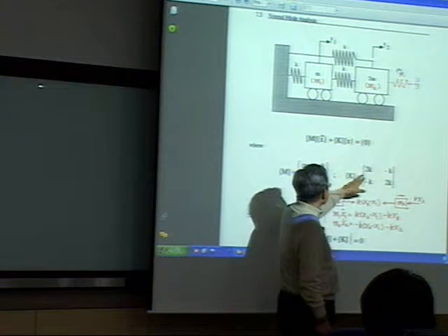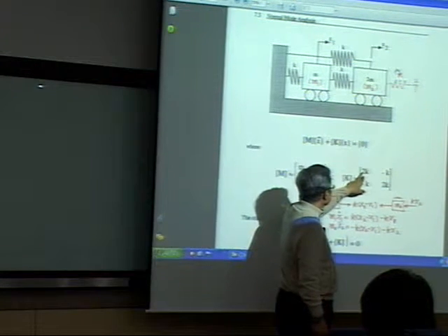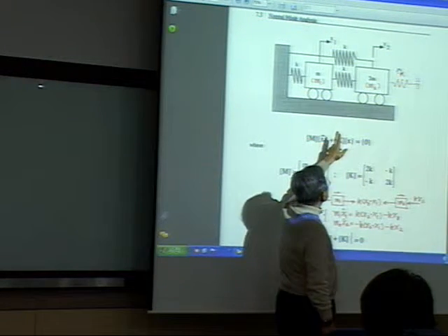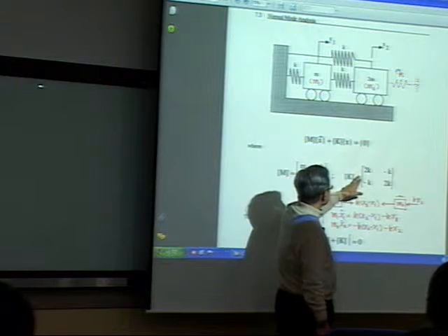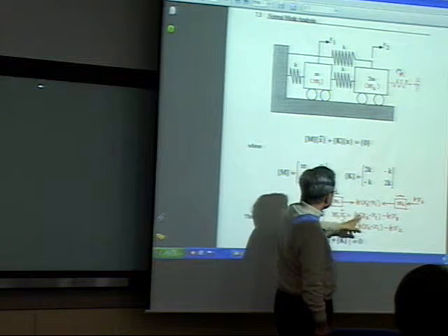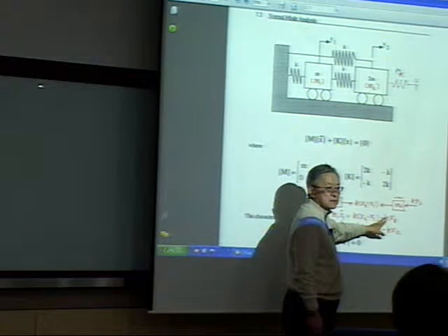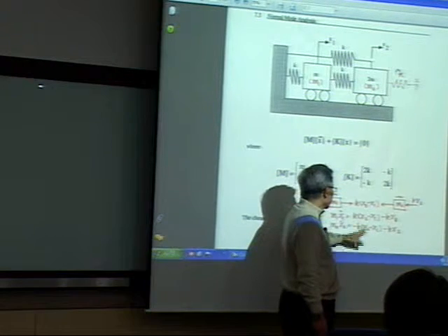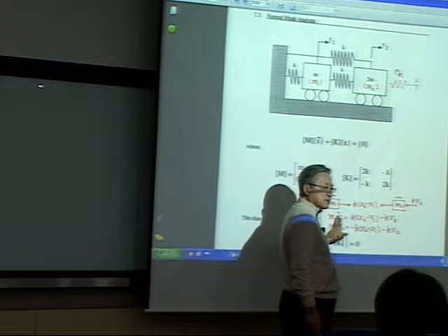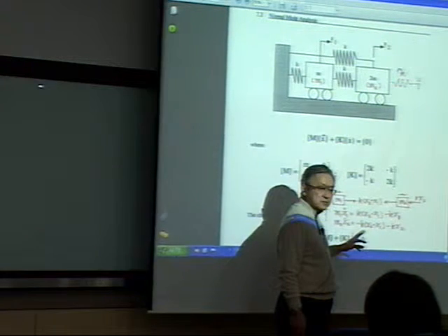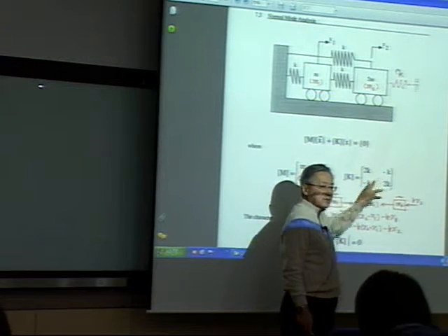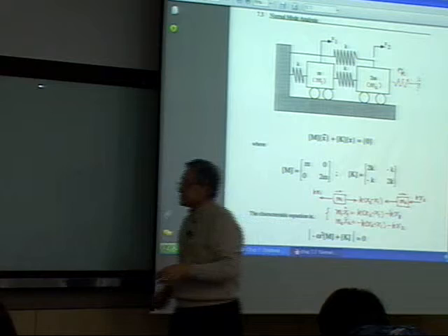The first term in the middle is 2k, right? I'm sorry, k becomes 2k because of the springs concerned. It's k and k, 2k. And x2 is concerned, kx2, when you move this guy to the left, it's a minus kx2. It's going to be negative, right? So that's the way you set it up very easily.